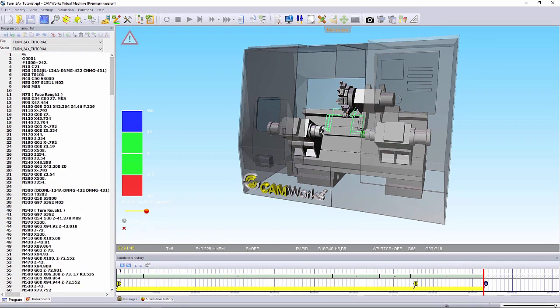Within this Gcode file, I can make adjustments to it. So I can overwrite, say, feed rates or XYZ coordinates. I can add comments, and I can save out a new Gcode file from this area.